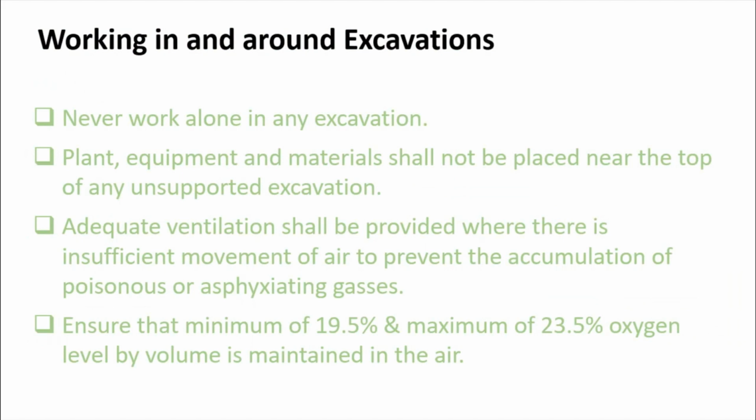Working in and around excavations: never work alone in any excavation. For the workers, you are not allowed to work alone in the excavation. Why? Because when you are alone, if something happens to you, nobody will rescue you and nobody will alert other persons to help you. So you should have at least a buddy system, with 2 persons as a minimum.